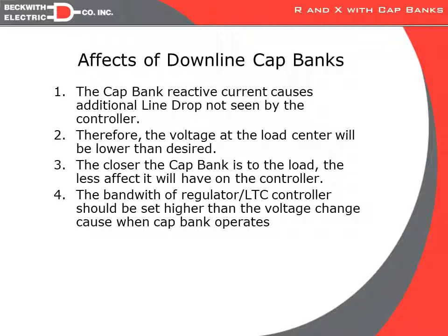So those are the effects that a capacitor bank, a switch bank, can have on a LTC or a regulator. Anything to the load side of that, the regulator or LTC cannot see that reactive current, and therefore if the capacitor bank is supplying reactive current, the regulator does not know that that reactive current is there, and therefore is not attempting to compensate for the voltage drop that is being caused due to the reactive current. But that reactive current voltage drop may be offset by the voltage rise given by the capacitor bank, depending on its